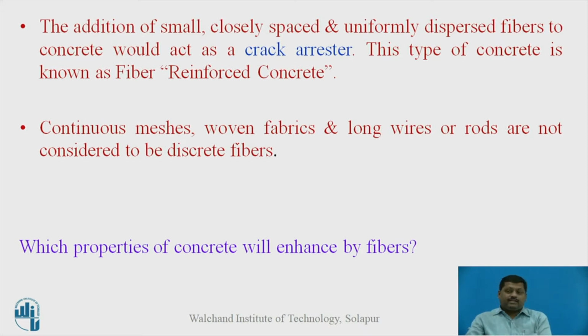Now we need some crack arrestor, which is the disadvantage of plain cement concrete. So the addition of some fibers which are small, closely spaced, discontinuous and uniformly dispersed into the concrete will act as a crack arrestor. So the function of crack arrestor is done by these fibers.